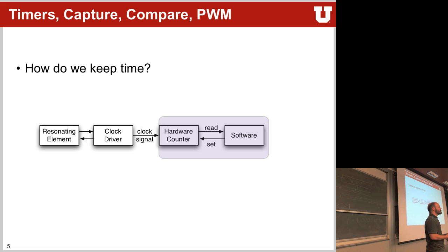The SmartFusion's timers cannot generate PWM signals because there's no GPIO unit that's connected to them. So they can't flip external pins. They have PWM units themselves directly, which work very similar. And I think, if I'm not mistaken, in Lab 5 you actually will implement your own PWM. Like you implement your own timer and have to flip a bit accordingly to generate a PWM signal.